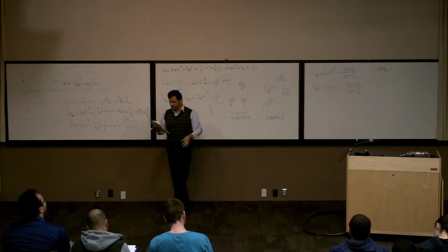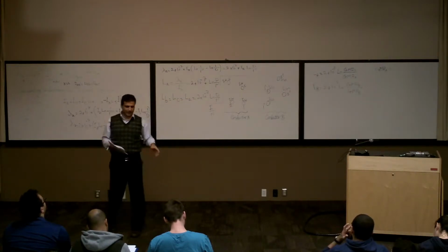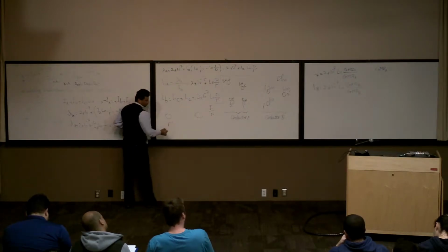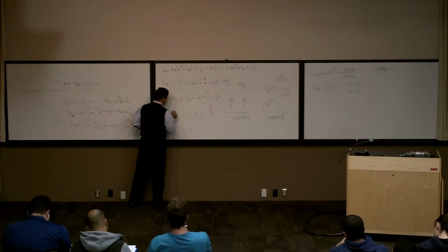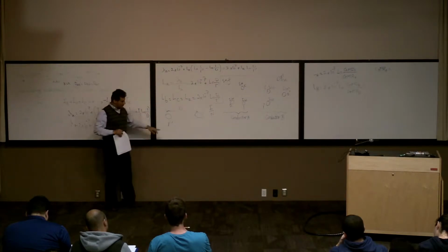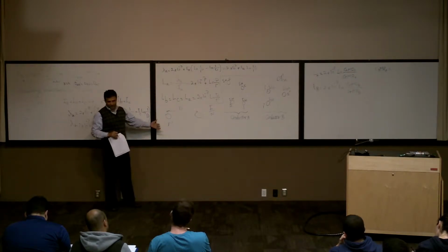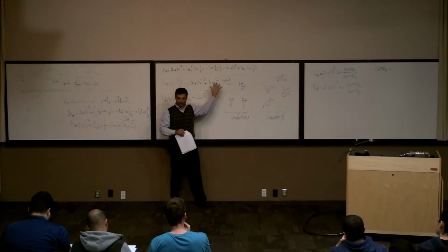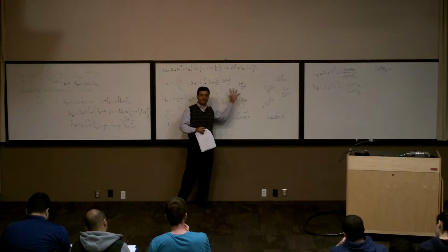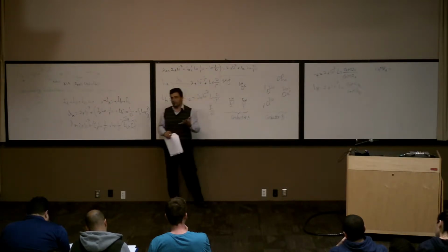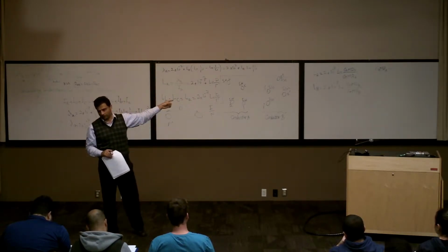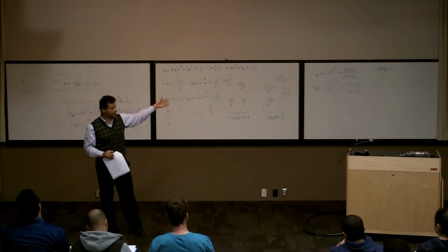The GMD, they call it geometric mean distance. Again, when we have 2 conductors, we look at this and this. For this one, we say R prime, right? And we say this distance is D, right? Now for R prime, it's not as simple as 1, because we have N of them here. Somehow we should come up with a kind of averaging method to replace this with the equivalent of one conductor. So how much is the R prime for that conductor? That's a GMR. We're going to explain how to calculate that.